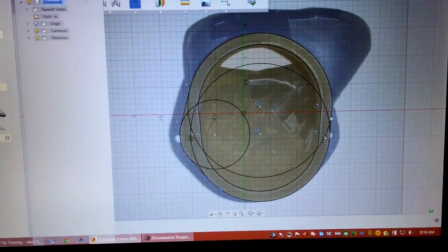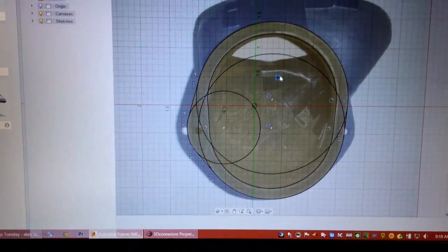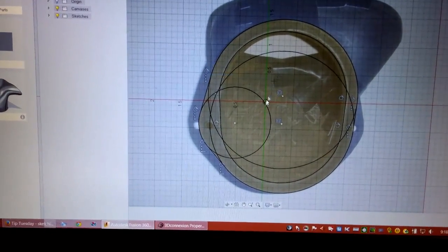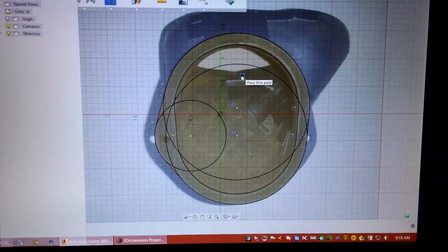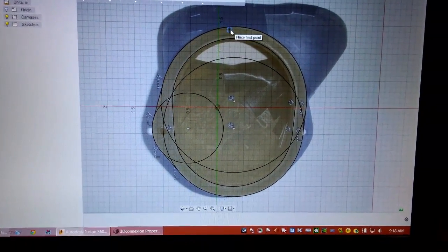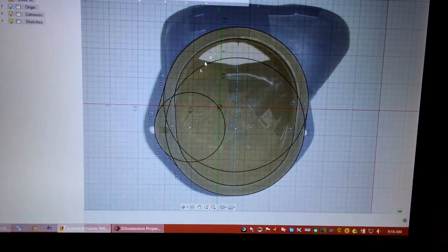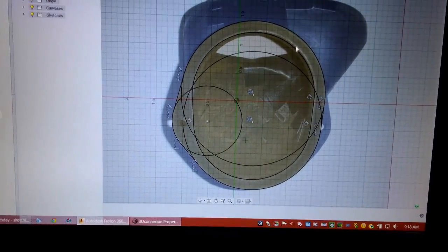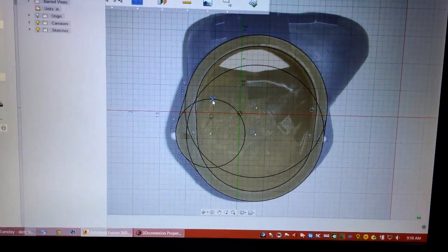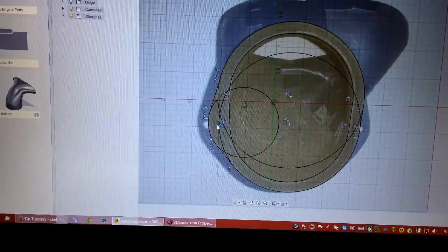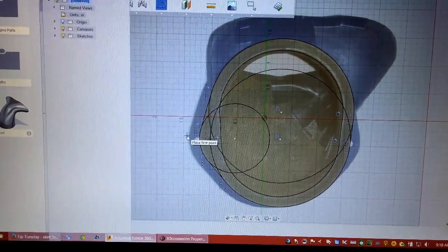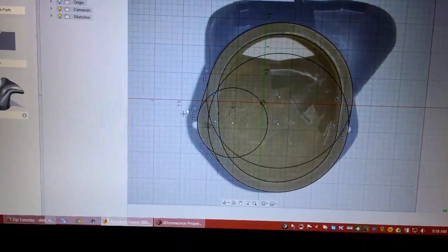Now, I don't have this set to the specific, correct dimensions. It's a matter of you create your sketch against the picture here. Then you eliminate the picture and you can scale the sketch. Basically I'm just going to create the flange here, and then I'll extrude it and make it, you know, like 1/8 of an inch thick, 100 thou thick.